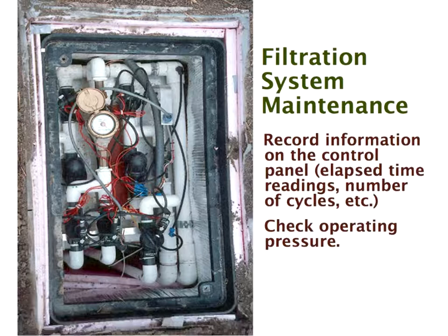Here's another filtration system, with the two filters. In the other picture we had, they were purple. In this case, they're black, but they're still disc filters. And this is the flow meter. And again, you need to clean these, and you need to check the 3 zone solenoid valves.